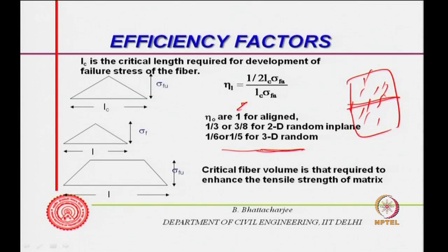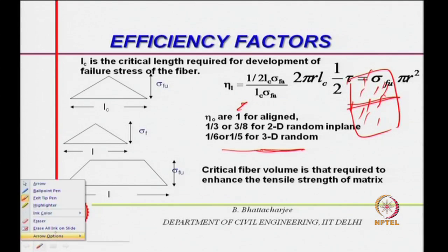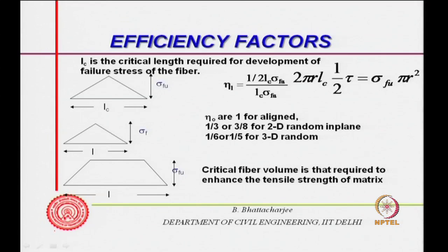When I have sufficient quantity of fiber, at least some fiber will be bridging the crack. So, right now, to understand that, we will have to look into how L c is related. L c is the critical length, that is what we said, and L c is actually related to sigma Fu r by tau. How? Let us just see, because the stress from the fiber to the matrix is transferred through